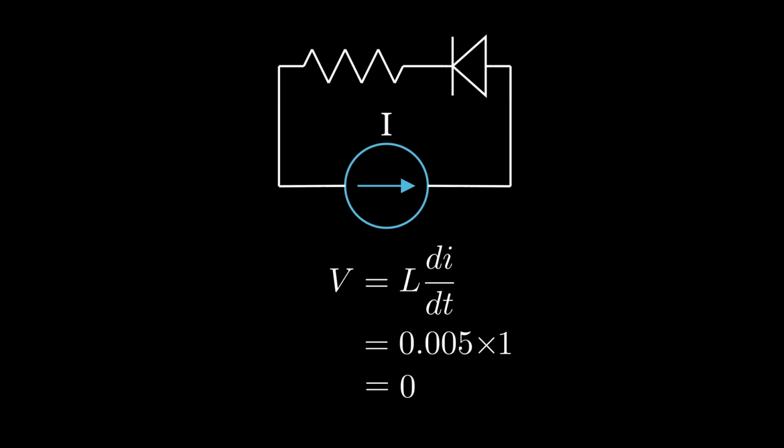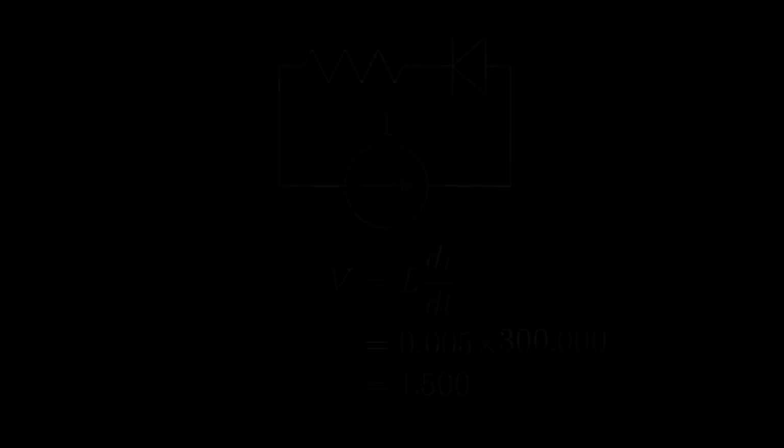Going back to the inductor voltage equation, the voltage is dependent on the change in current in respect to time. So the faster the current changes, the higher the voltage across the inductor will be for a given inductance. This voltage spike can be lethal to our switch components if it exceeds their voltage rating. So what can we do now to decrease this spike?